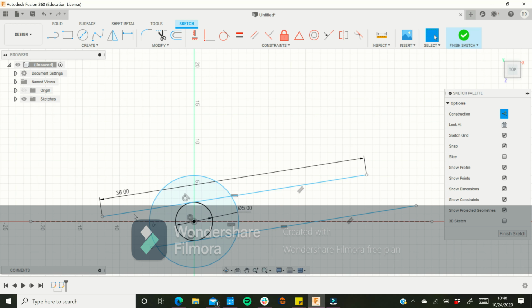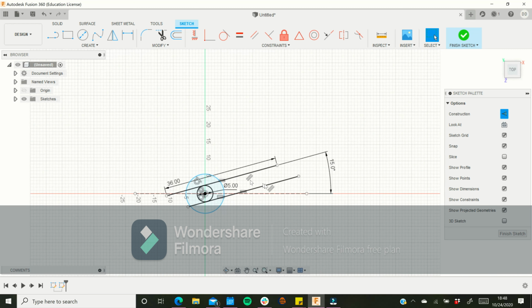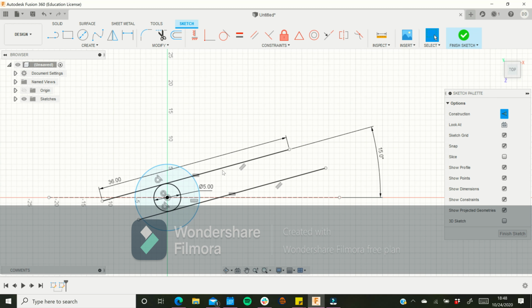Now I can define this line at an angle from that construction line. So now I have this nice angle, and that will constrain both of those lines because those lines are equal. They have the equal length and they're both tangent to that circle, and I'm dimensioning this angle. Let's make it 15 degrees. And yeah, now all I have to do is constrain this circle. I'm going to constrain it based on this dimension because that was a thing that we've gone over. I'm going to select dimension, click on the outer circle, and I'm going to set it like this. Let's say I do want it to be 12. I want it to be a foot in diameter. I'm going to select this one and just say +7.